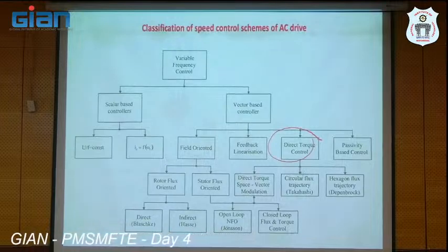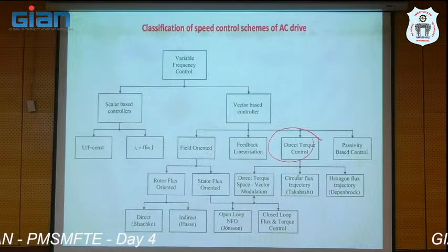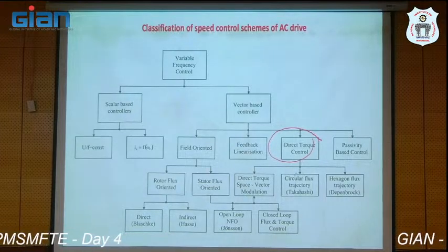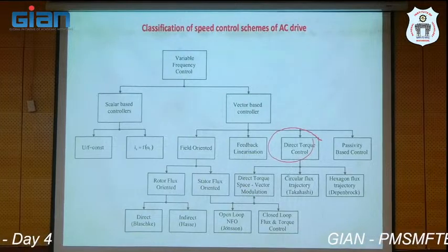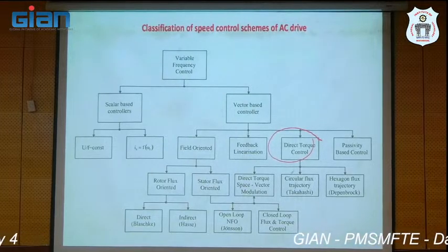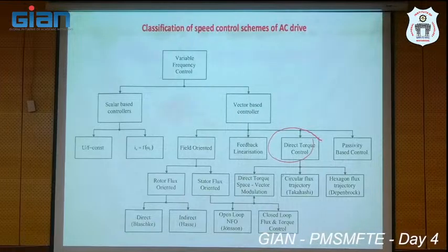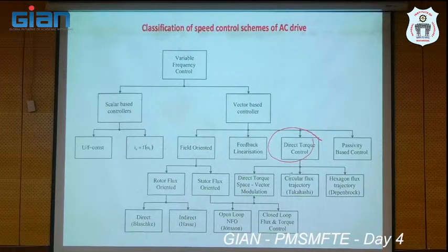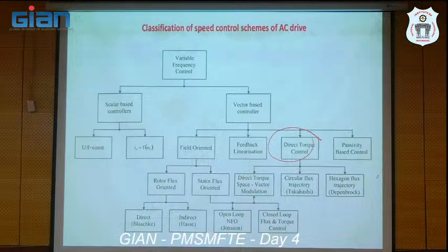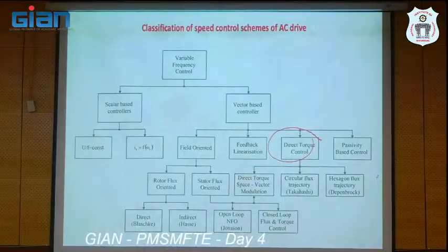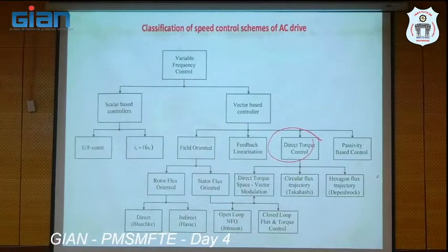Without V/F, we cannot minimize the number of variables involved in the torque expression. Without the V/F method, we cannot produce maximum torque even when the operating speed is low. You got my point? V/F is common for all methods, whether scalar control or vector control.